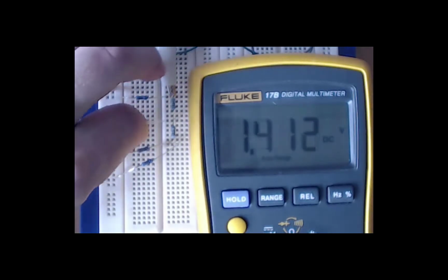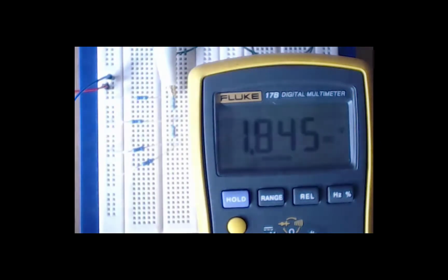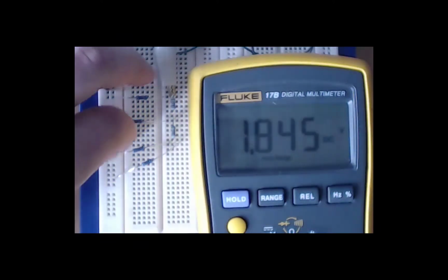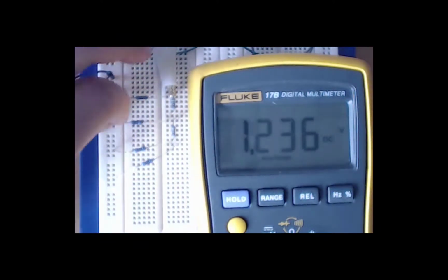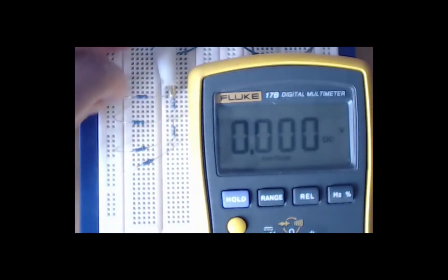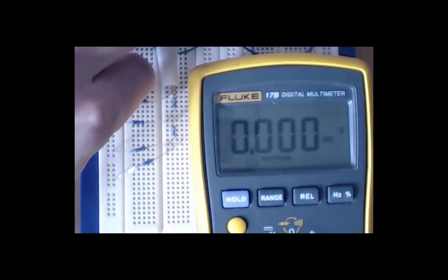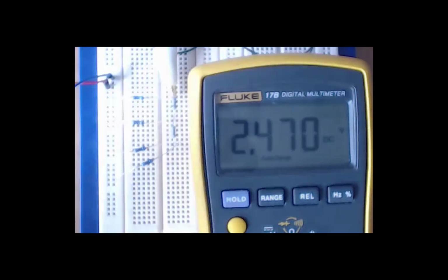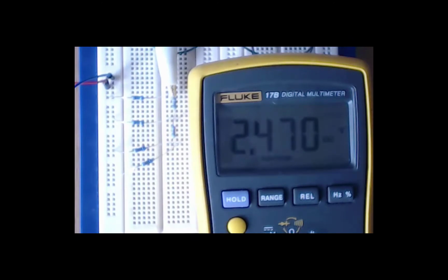We step up and put the value 3 in there, we increase by about another 0.6 volts as well. If we step these low and move our most significant bit, it should give us about half our full scale voltage, so about 2.5 volts or so. That's a very basic example.